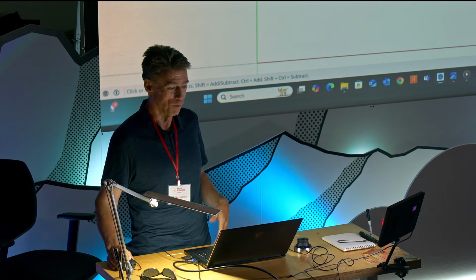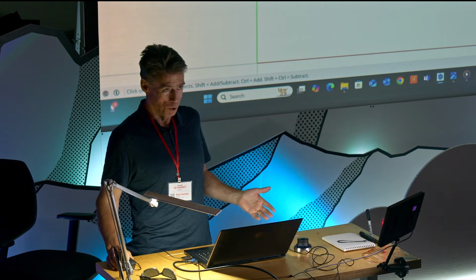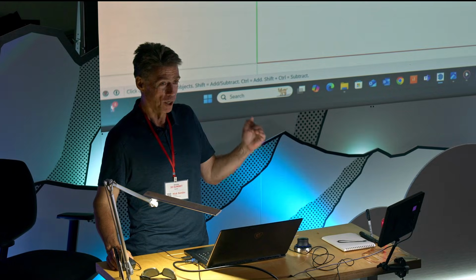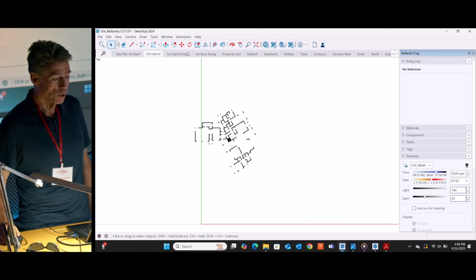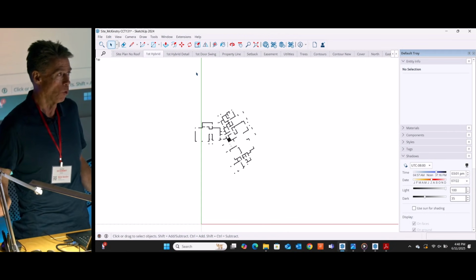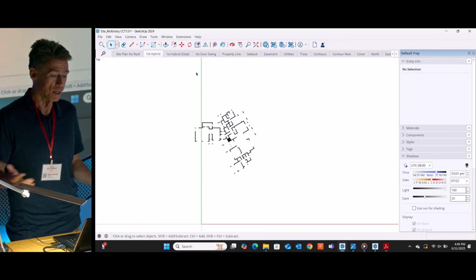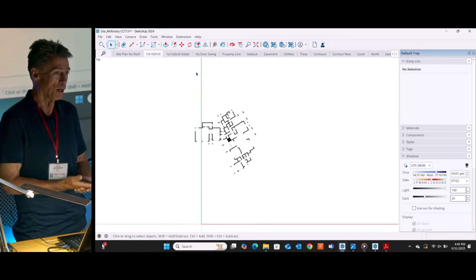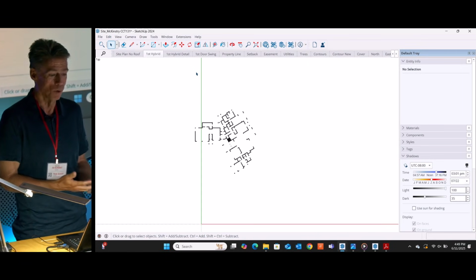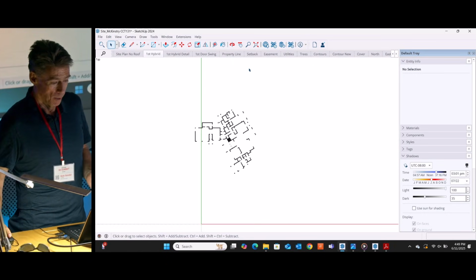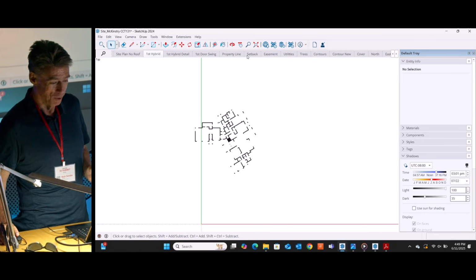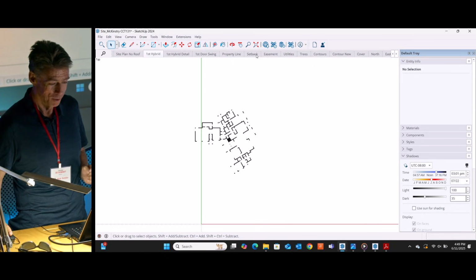So a 3-foot door is a 3-foot 2-inch wide opening, 8-foot 1-inch tall. I try to keep all the studs at least at one end. If it's a shed, at a standard stud height, you know, 8'1", 9'1", 10'1", 12'1", and so on. Because if you make your builder happy, they like you, and they're less likely to throw you under the bus.